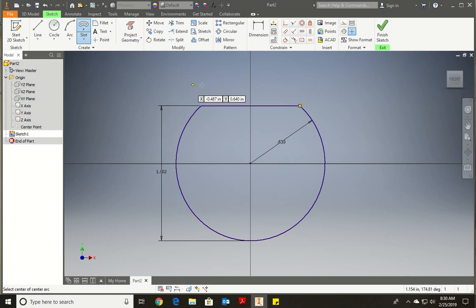From there now, we're going to select the origin, because that's our first point. Then we're going to click one line on this location and one on the opposite side. And then you could pull it out to give it a thickness. If you knew the diameter right away or the radius, you could type it in, but in this case we'll add it on later on. So there we go. So now we have it set.